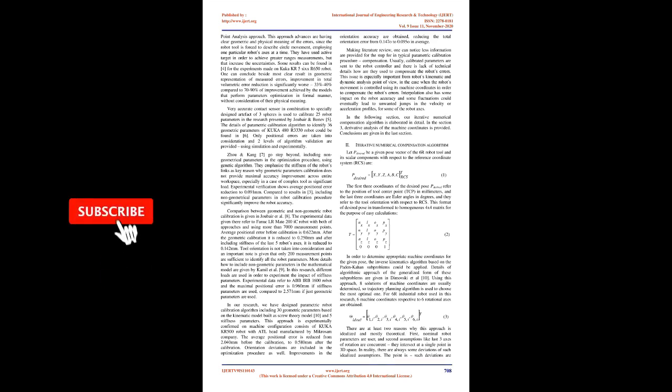Similar research is conducted by Santolaria et al. [4], taking a specific choice of measurement points made by a circle point analysis approach. The advantage of this approach is having a clear geometric and physical meaning of the errors, since the robot tool is forced to describe a circle movement, employing one particular robot axis at a time. They have used an active target in order to achieve greater measurement ranges, but that increases the uncertainties. Some results can be found in [4] for the experiments made on a KUKA KR 5-6 R650 robot.